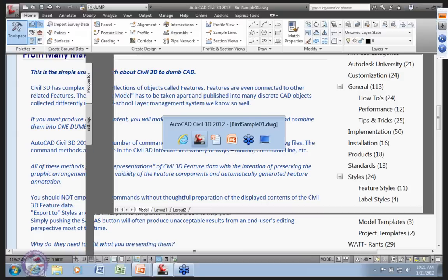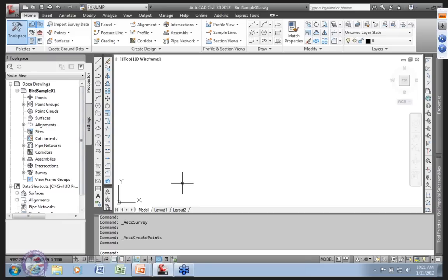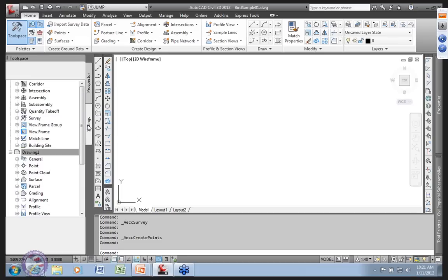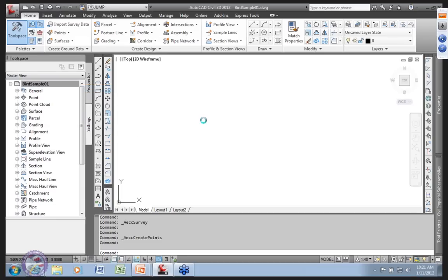Okay, so inside Civil 3D, let's get to some data. A couple of things. We've got a drawing. It is in a coordinate system. We did that over in the settings tab, Edit Drawing Settings. It happens to be the California state plane because that's where this project is. Now, if you don't want to ship the coordinate information, you can do that to them. But check, make sure. Other issues, since we're going to be working inside a survey here and employing a survey database to barf what we need onto the screen and get it in the format that we want.